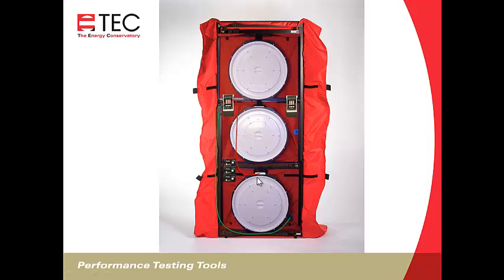So this is a setup for a single fan system. This is how you're always setting up. And then for the second gauge, the gauge on the right, we'll run a tube from input on channel A to the second fan, and then we'll run a tube from input on channel B up to the third fan.